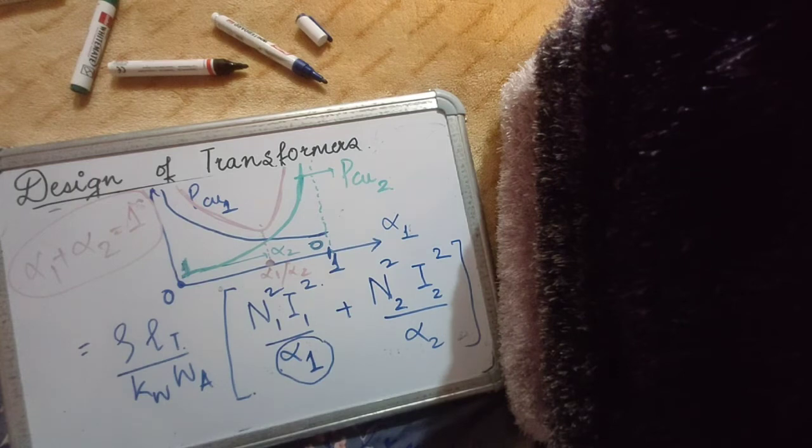You have to also take care of the maximum flux density, just like inductors, and you also have to take care of the step up step down ratio, so n1 is to n2, and the dot convention as well, the selection of the core, choosing a small sized high flux density core such as a ferrite core. So all these things are very similar to inductor design, just that there is another set of winding and you have to accommodate it within the same core.